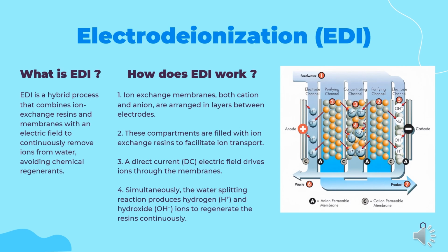The water dissociation reaction during EDI operation produces hydrogen ions, H+, and hydroxyl ions, OH-, which continuously regenerate the ion exchange resins electrochemically without using regenerating chemicals. This innovative electro-regeneration eliminates the need for chemical regenerants and provides a consistent deionization process.